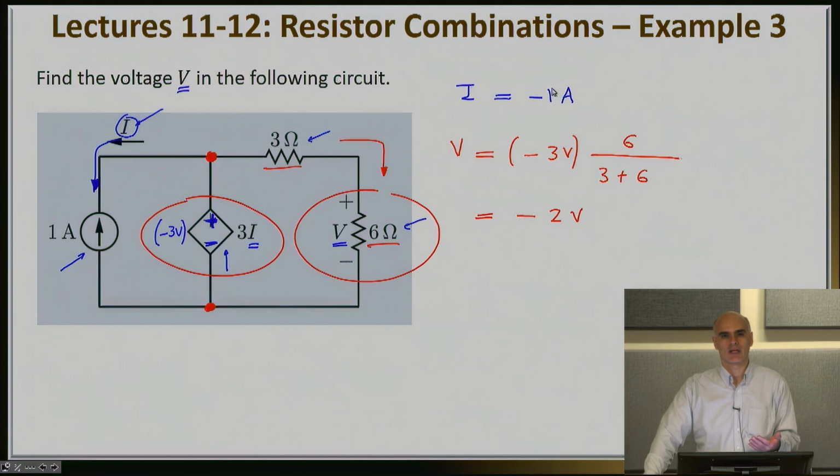We have learned how you can combine voltage sources when they are connected in series, or current sources when they're connected in parallel, but we have never seen how to combine two dissimilar devices like a resistor and a current source, or a resistor and a voltage source. You can't do that, so don't spend time thinking if there is a way for me to simplify the circuit.